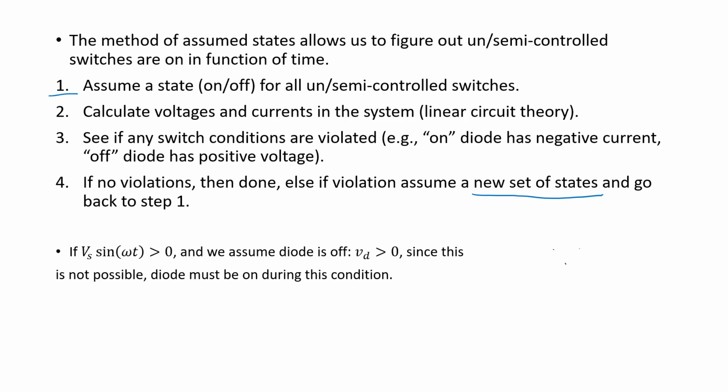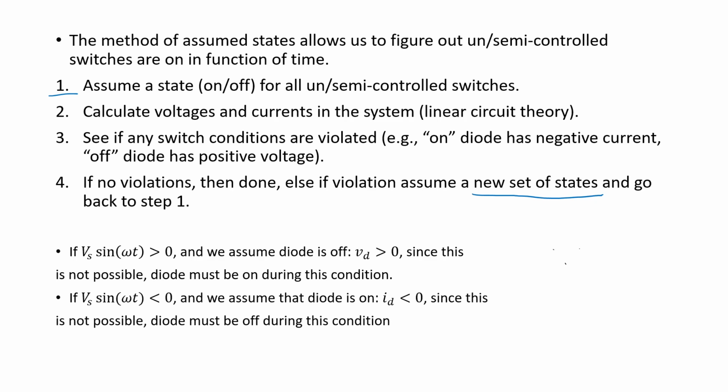A very simple case for the rectifier. When the source is positive, and you assume that the diode is off, when you calculate, for sure you get positive voltage on the diode, then it's wrong.